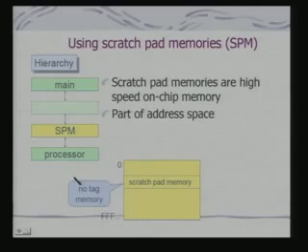So if you look into it, what we are looking at is a processor, and I have got SPM. This can be cache memory, and this is the main memory which gets mapped onto cache, and this SPM is part of the address space. And that's why I'm referring to this as no tag memory, because if it's a cache, then it has to be tagged.